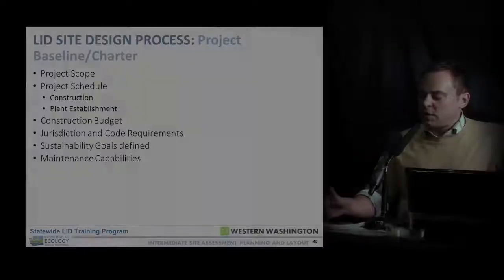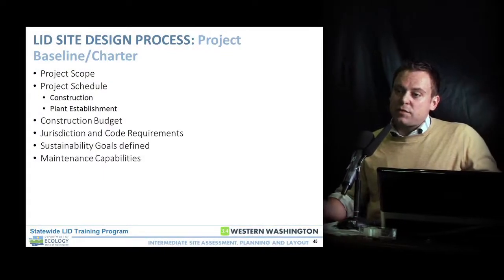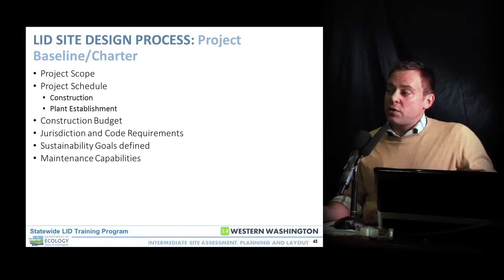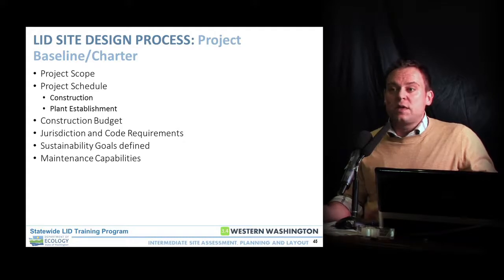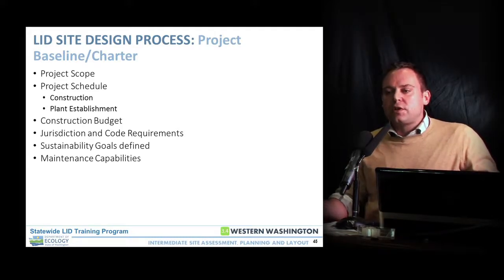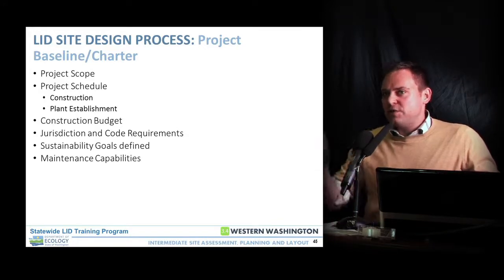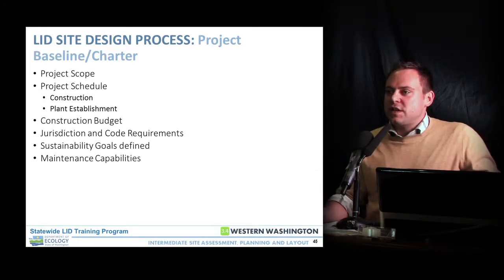And again, this is really important not only from the planning perspective of doing the design, but also for construction, because weather requirements are important for knowing when you're going to assess high groundwater tables, as well as when you construct the project. You're not going to generally want to do low impact development projects during January. Granted, today's a beautiful day, but most of the time we're going to have rain, which is not a good time to be going out and exposing soils for infiltration.